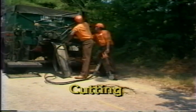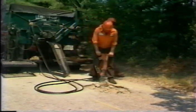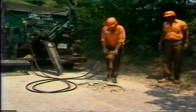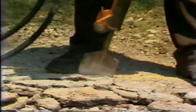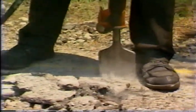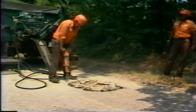The second step in the patching procedure is cutting. Cutting prevents damage to surrounding pavement when removing material and provides a vertical face for containment and bonding with the patch material. Use a pavement cutter to cut out the marked area. A sharp bit improves the cutting rate and reduces the damage to the pavement during the cutting operation.